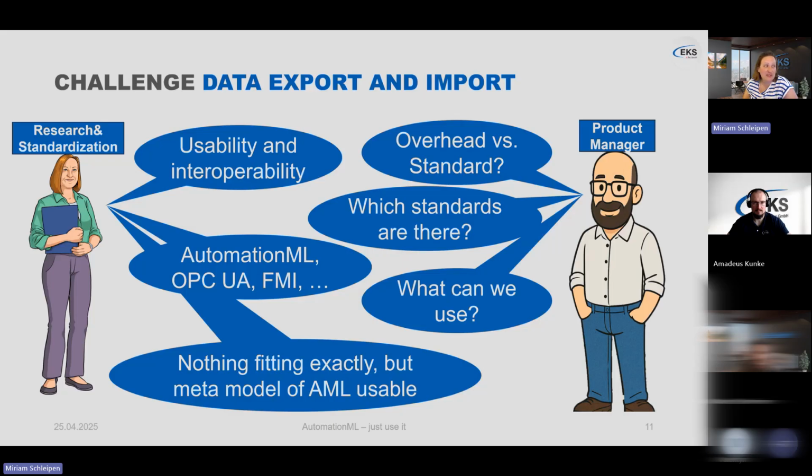Even if something changes, even if at a later stage there is something dealing with process analysis, process optimization, the description of processes, or any other thing, even if now there is nothing completely fitting, you have the basic structures in the standard. So you have the concept, for example, in AutomationML of role classes to define the semantics of the elements you model. You have the possibility to define attribute types. You have copy templates, the system unit classes, for different structures. And all that is already there and usable.